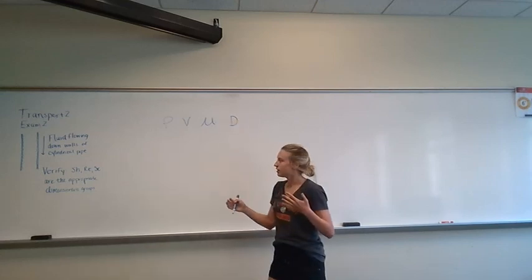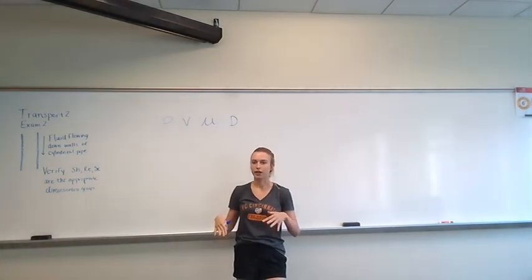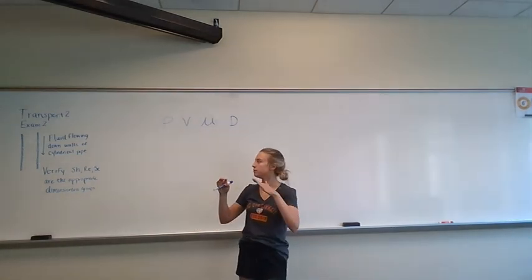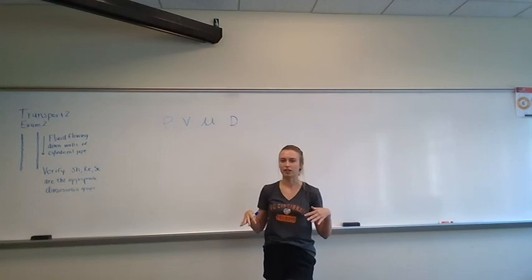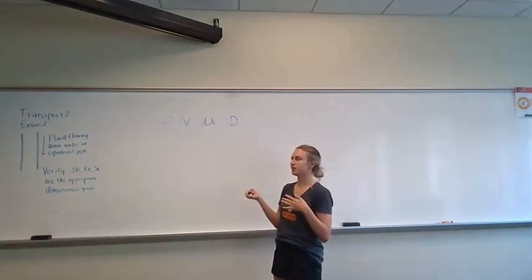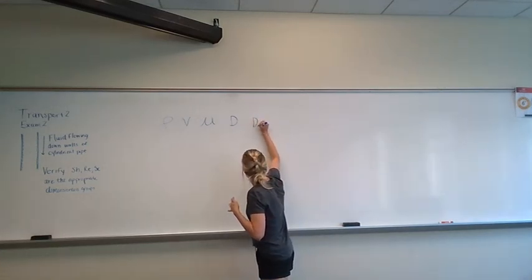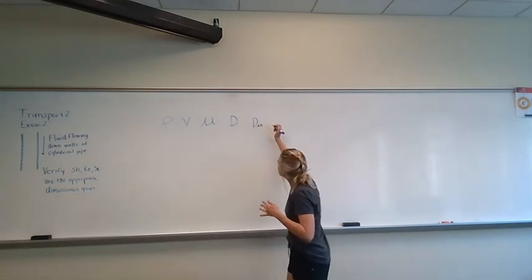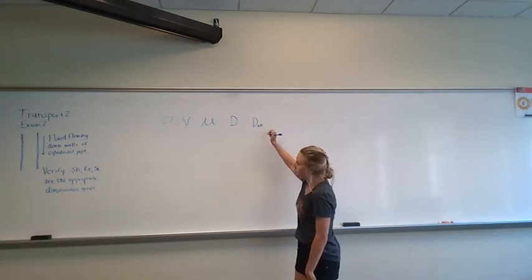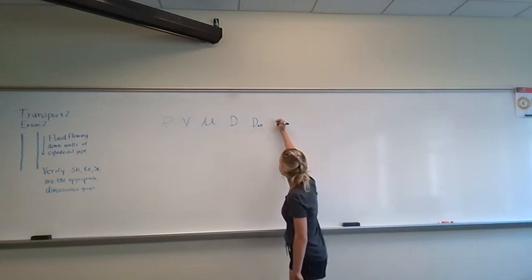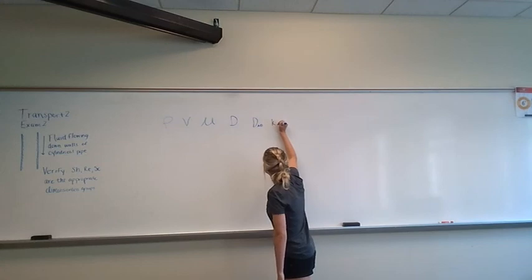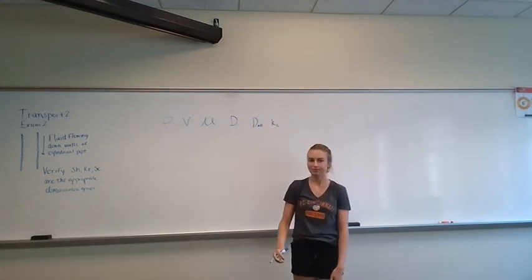And then we know that since the fluid is flowing down the walls of the pipe, there will be some gas in the center of the pipe, and the fluid will be evaporating and diffusing into this gas. So we need to know the diffusion coefficient between the fluid and the gas, DAB. And then finally, we need to know the mass transfer coefficient, Kc.